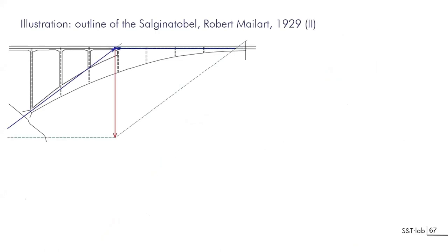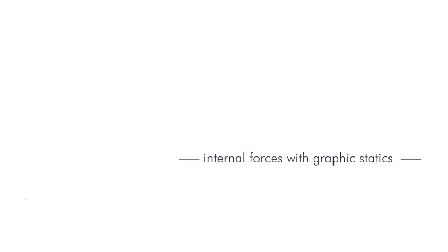And actually, if you seek the equilibrium, as I will be demonstrating later, you have a symmetrical system with a horizontal thrust line here, equilibrated with the resulting applied forces. And you know, from this point of intersection and from the center of the hinge, what the direction of the reaction force will be, which will enable you to make the calculation. I will show this in detail later on.